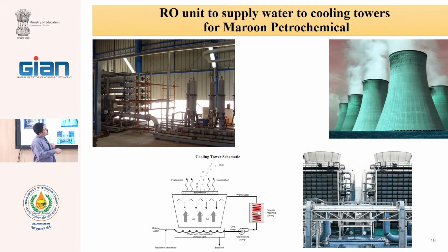This is the very simple type, but in this type we have some trays, some cascades for increasing the water pass, and the height is lower. This is the 50 meters. This is usually 20 meters. But simply, with evaporation, the temperature of water is reduced.